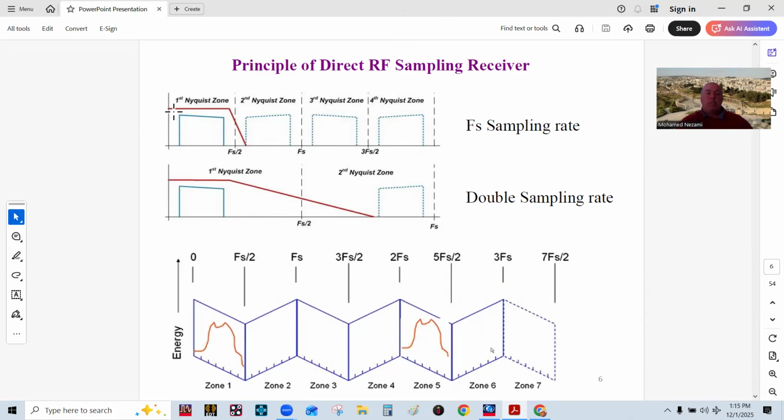In which case, what you're doing is the frequencies in the analog world are just going to be transformed to the digital world, and there is no need for digital down conversion like we introduced last time. So that's easily done, and that's what people have done in the direct conversion receivers, basically, and some of the low IF sampling receivers.